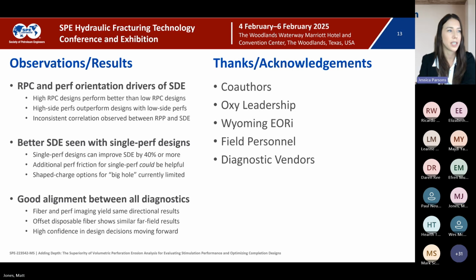Did all the stages have full design rate before the sand started? That's a great question. I would say that the majority of them did. I can't quantify it for you, but when we were treating this well, we didn't have any rate limitation issues. There may have been a couple of stages at the toe that could have been slightly rate limited before we got proppant on bottom and started seeing some erosion and reduction of surface treating pressure. But I did not get the sense as we were treating this well that we were severely rate limited.